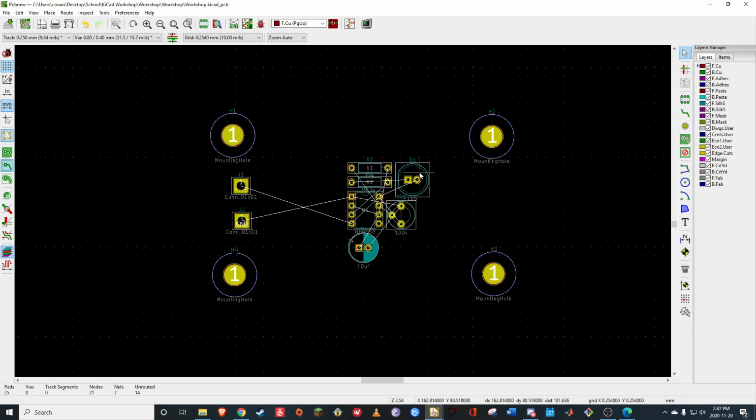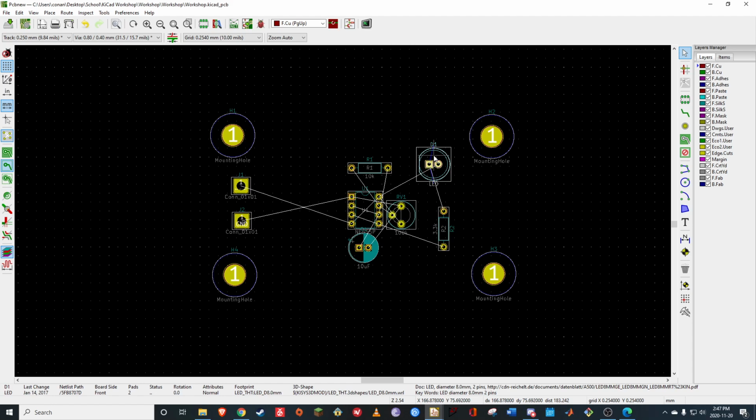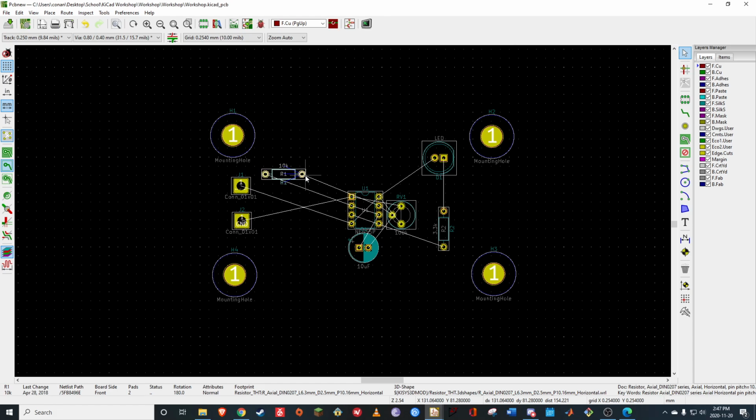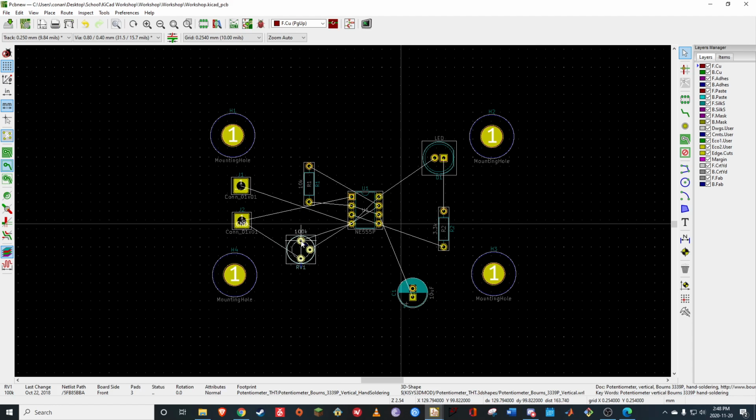Okay. Now we remember our diode was up here somewhere. We had resistor 2 going directly into the diode. Now these white lines are telling you which nodes are connected to what. They're not physically there. You'll have to put the traces in yourself later. Again, R makes things rotate, in case you're confused by why all of my components are flipping around as I'm doing this.